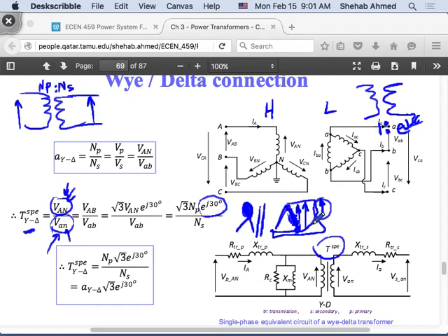So I have this transformer now connected to a fictitious load. I would like to see what the voltage is on the single phase equivalent circuit that I want to replace in my equivalent impedance diagram for the system, right? So here between this winding and one winding here, there's a turns ratio. This turns ratio is equal to the primary turns over the secondary turns. This one has NP turns. This one has NS turns, right?